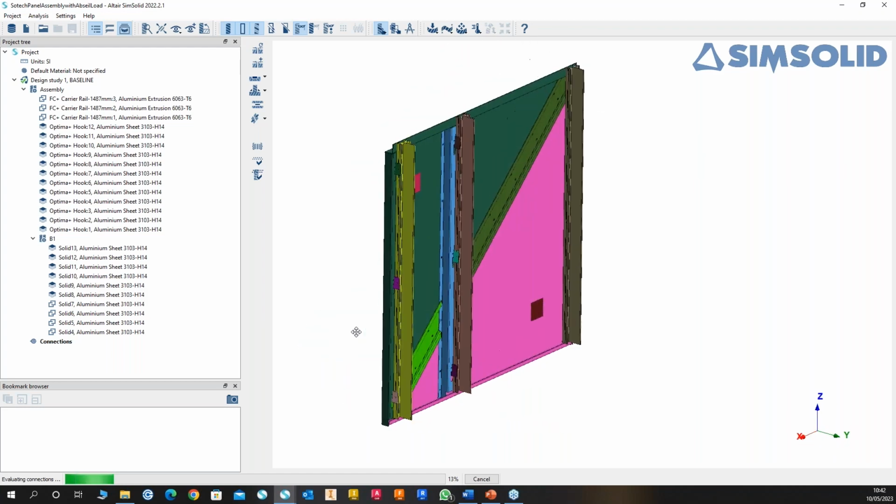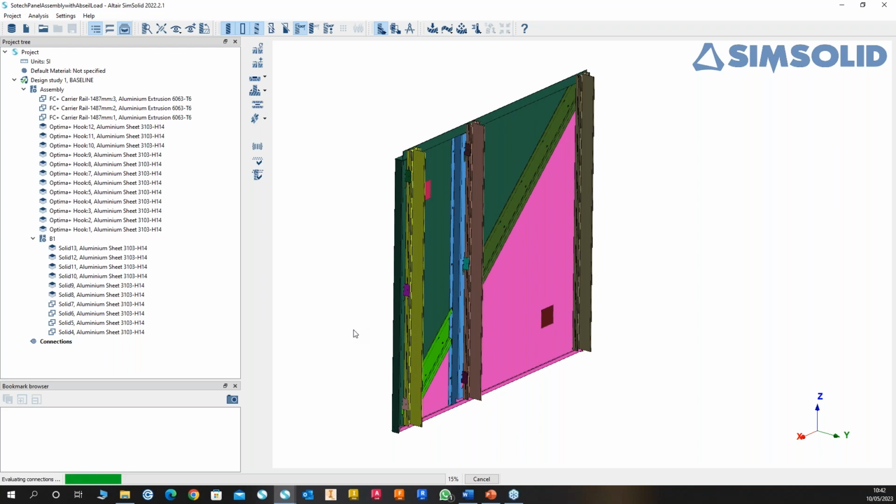Now, Watson mentioned something which was the bolt and nut connection, which is very robust. But what you've got to bear in mind is, for a bolt connection to be recognized as a bolt, you need to have the head as a hex head. That's one thing that drove me mad to find out: if I've just got a simple pin there, why does it not recognize it?